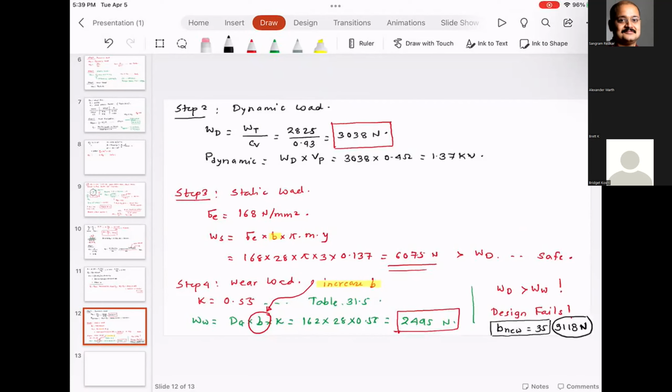It's not an area contact, but one gear is scraping the other gear, which means you are going to have very high localized stresses. What would that localized stress do? That localized stress would cause some type of localized deformation, and this continuous deformation on the contact surface would result in pitting. What is pitting?